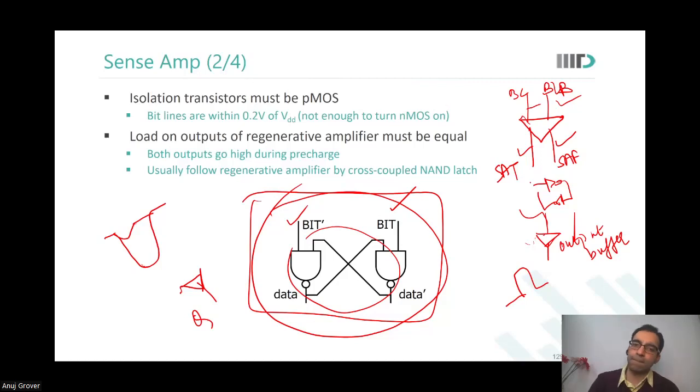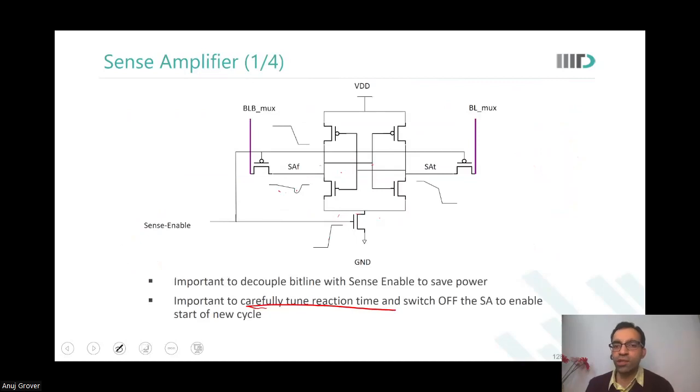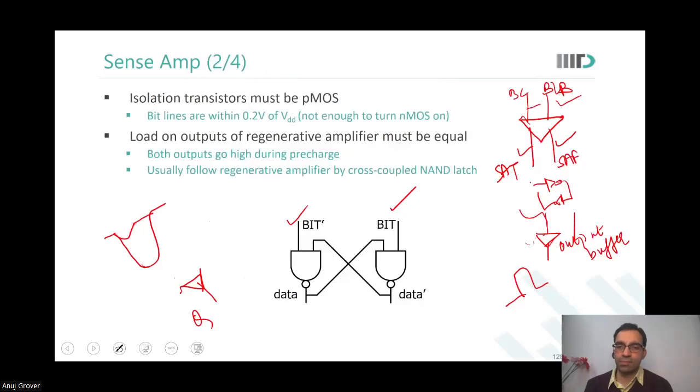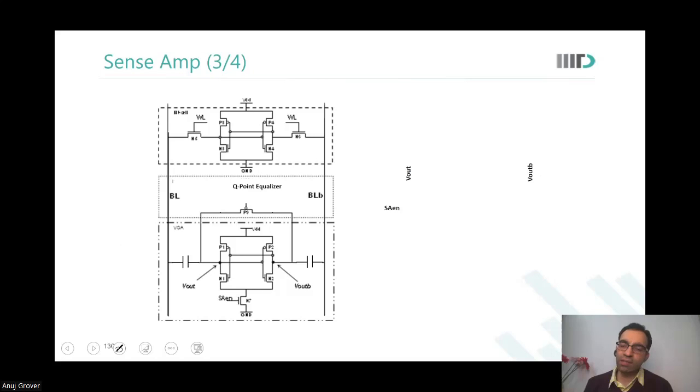So in the sense amplifier, the SAF and the SAT nodes that I was taking to this, I was taking the output, sir, because it was not evident to me from that example. What is the output then? What got amplified from VDD and VDD to 0 and VDD? So the SAF and the SAT nodes. So that is the output, no? Yes. And so these two nodes you are taking to the latch? Yes. Okay. So that was one set of sense amplifiers.